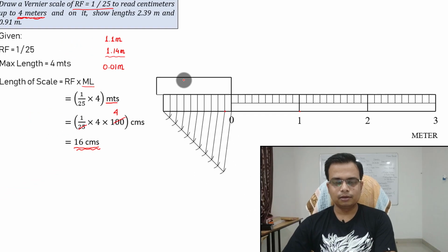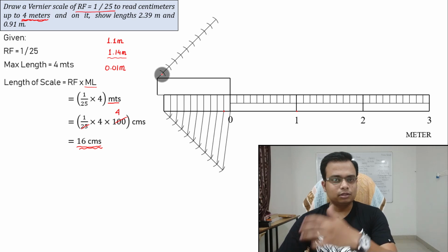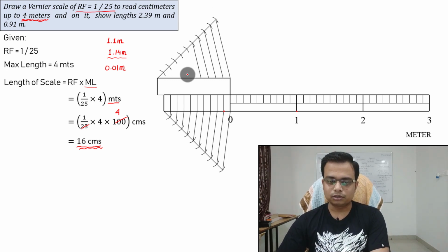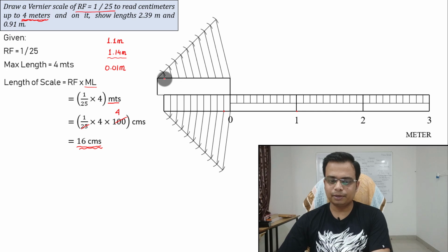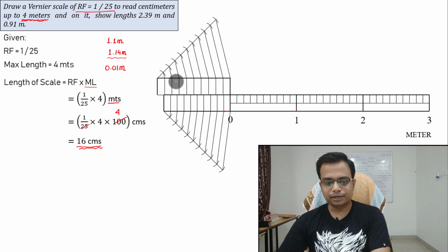Join them. Now the number of divisions that happened over here were 10. The number of divisions which you need to do here also is going to be 10. Again the same process, the line division technique. Have 10 arcs. I have taken the radii of these arcs as 5 millimeters. Do this. Very simple, very basic. Drop vertical lines from all these division points.